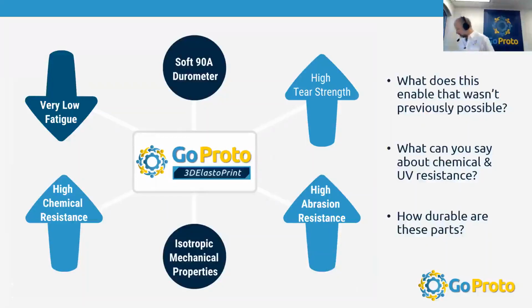Great question. That's actually one of the reasons why we've worked a little bit harder. I've got a TPU part here versus the TPA part. The surface feel of them, they both kind of have a grainy finish because they're just bead blasted. There we go. So the TPU part feels kind of hard and slippery. The TPA part, the material that we're talking about here, is much grippier. Just its basic finish is grippier. It feels more like what you'd consider an elastomer feel. It doesn't feel crystallized on the surface. Grippy like rubber, not like photopolymers that I've felt where you're picking up dog hair.